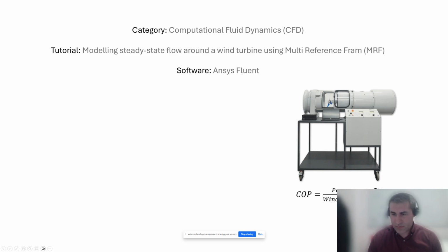The power of the rotor is torque times the rotational speed. Torque is represented by T, and rotational speed of the blade of the rotors is going to be represented by omega. And the power of the wind is half of rho A V to the power of 3.